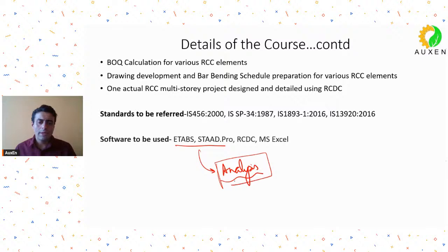So only for bringing the analysis file from ETABS or STAAD.Pro, we'll be using these two softwares, and then we will be referring mainly to RCDC, and we will be taking help of Excel spreadsheets for the verification of results, so that we are able to verify what RCDC is giving as output.